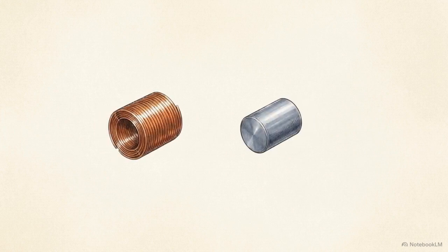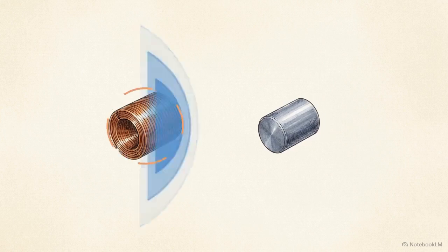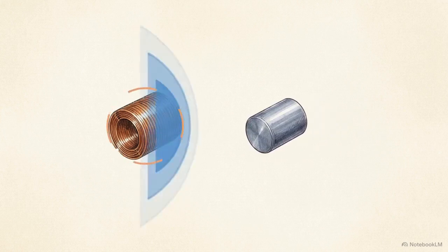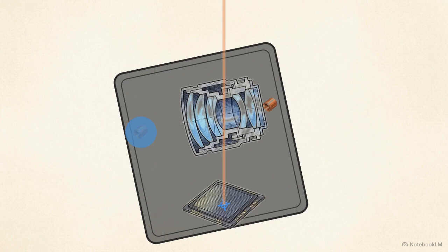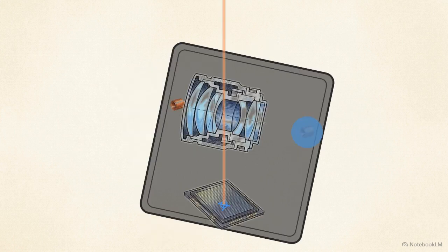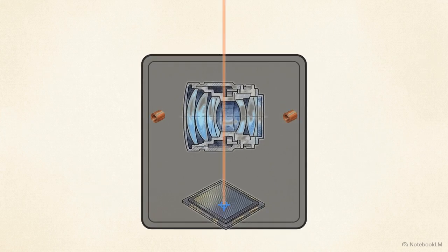These actuators operate using a simple physics principle. Running an electric current through tightly wound miniature coils generates a controlled magnetic field. In this animated cross-section, we see compensation. If the phone casing tilts downward, coils generate a magnetic field pushing the central lens upward by the exact amount. Because the lens moves oppositely, incoming light remains perfectly locked on to the image sensor below.